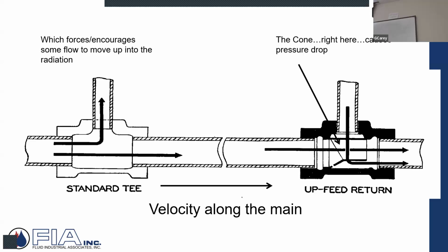Well, they oversized this piping, that one engineering firm, and then the other engineering firm on the main undersized it. So the flow getting into each building was a little too low. And then the piping it was going in was too big. So the point was the velocity along here was too slow. So it didn't create the pressure drop here. So it didn't cause the flow through the radiation. They get 10 buildings. I mean, the big problem.